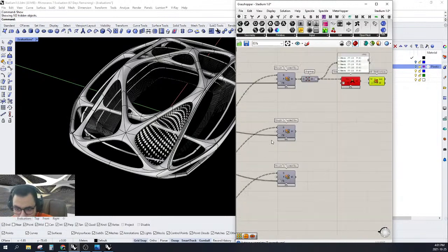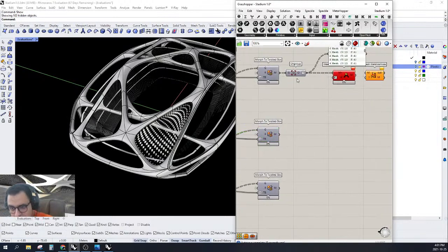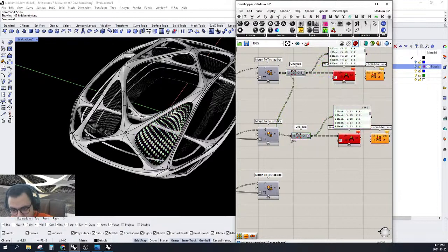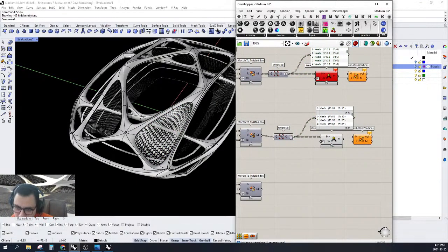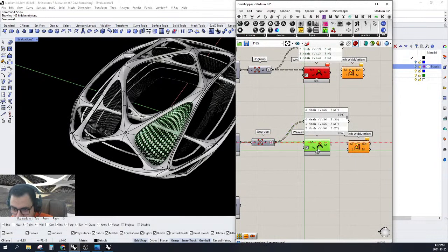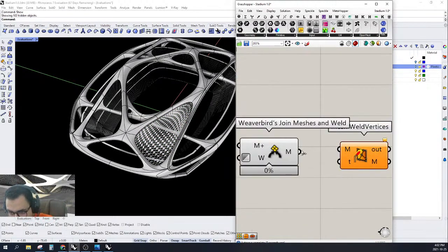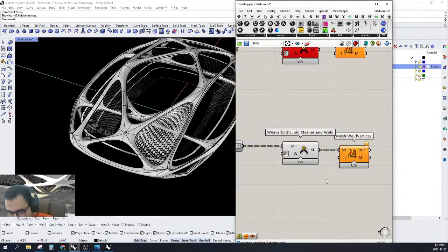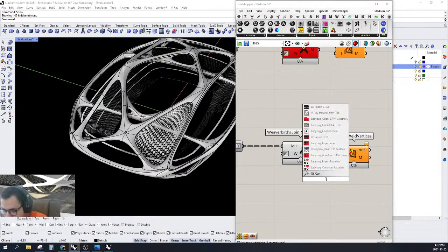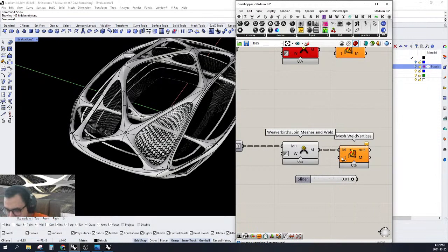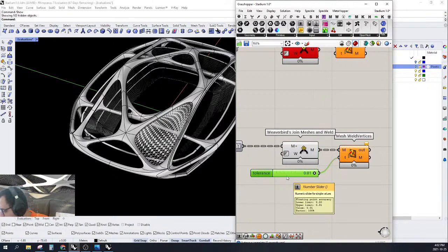Okay, let's ignore it in here and jump to here. And again, Control C, Control V. Just try. Yeah, it's working in here, of course, but in the first one, it's really annoying. I don't know why. But for now, of course, you need to jump in here and put a tolerance 0.01. Combine and clean.